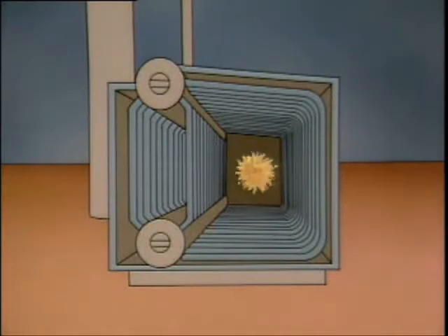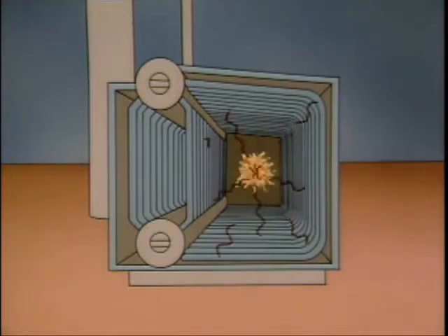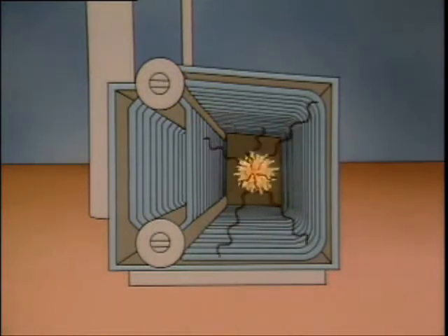When fuel burns in a boiler, radiant energy in the form of electromagnetic waves is produced. These waves travel through the combustion area. The waves in a direct line of sight with the tubes make contact with the outer tube surfaces, and the tubes absorb heat. This is radiant heat transfer.